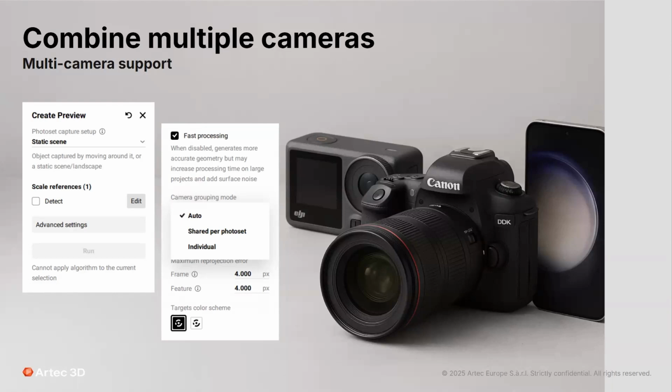And then we have two different options. You should select the individual option if you import all of your photos from all your different cameras at the same time. So if you just drag and drop the folder which contains all the photos from different cameras, then once you are going to do the photogrammetry, it's best to select the individual mode.